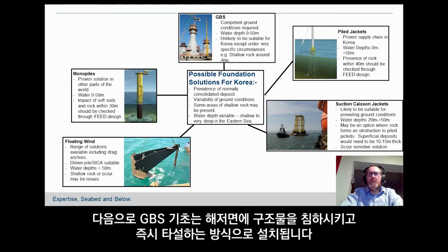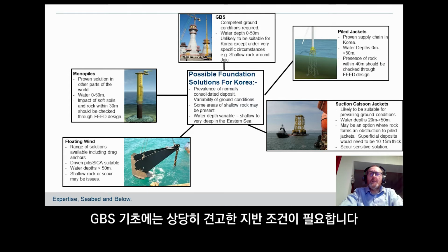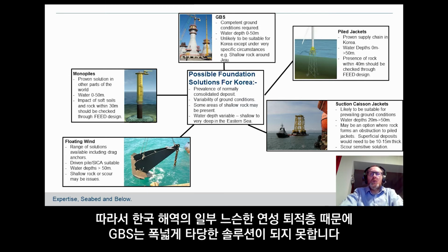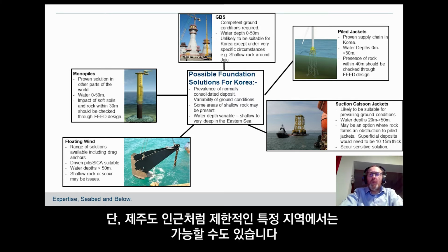Moving on to GBS foundations, large structures which are sunk to the seabed and are supported on the seabed immediately, and these require quite competent ground conditions. Given the soft and loose nature of some of the deposits around Korea, it's unlikely that this is going to be a viable option for those conditions, except for very localized areas such as around Jeju, for example.